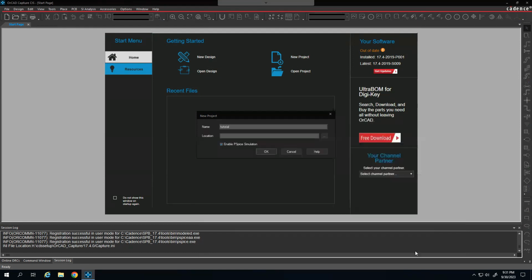Create the folder and select it. Now all the projects for this session should be saved in this folder. You don't have to feel too attached to this folder as it is mostly temporary and we won't need you to access all the projects for future labs. Also double check that this option is enabled to make sure that our PSpice simulations are actually enabled.